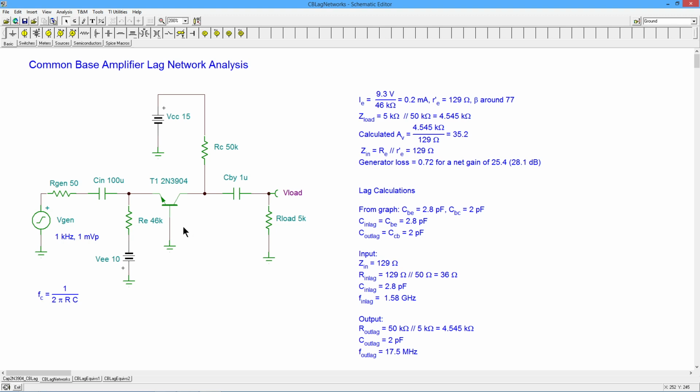So, like I said, you're kind of stuck. Now you could put big capacitors out here. You could say, I'm going to add a 1 nanofarad capacitor, and you would come up with an appropriate frequency. That might be perfectly valid if for some reason you had a really large input capacitance, some cabling or something that you had to deal with. But otherwise you're not really cross-checking the model. You're really just checking this other big external capacitance.